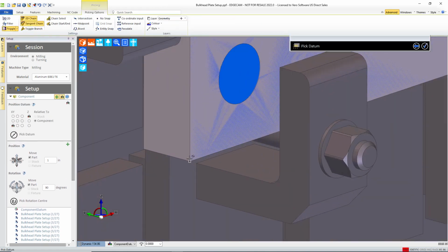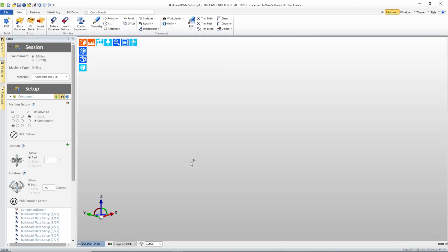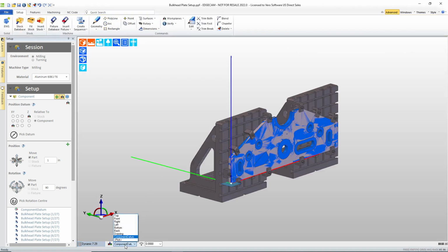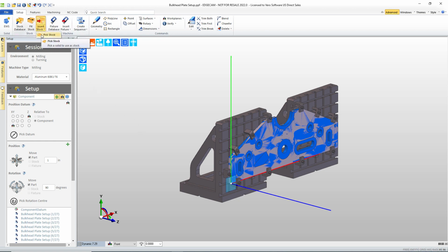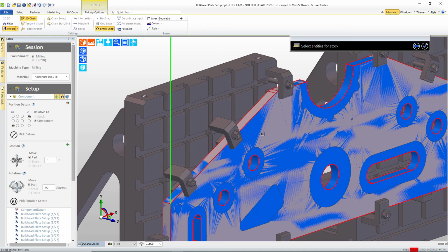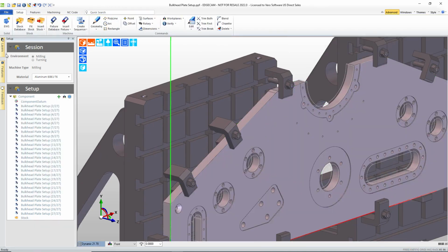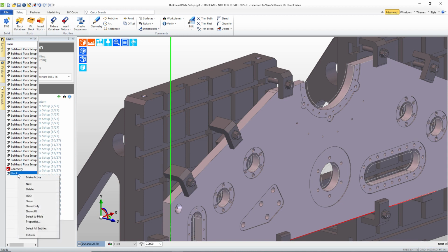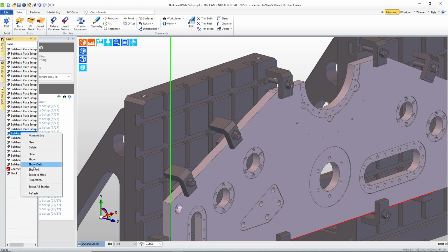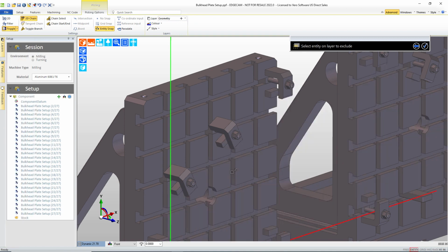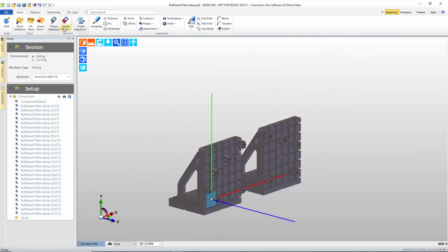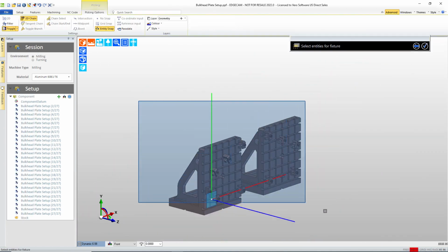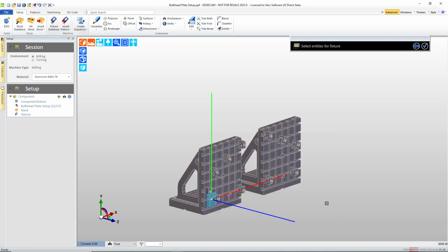So I want 0 right there on the corner. We'll snap to that. The solids immediately move to that position. This is going to go into a horizontal machining center, so I'm going to set up my datum to be what I prefer to use for horizontal machining centers, and then since this solid assembly contains everything, we'll say this solid is the stock, and it's put onto the stock layer automatically. So I'll hide that and the finished part, and then I'm going to use a similar command for fixtures and say all of your visible stuff are my fixtures.